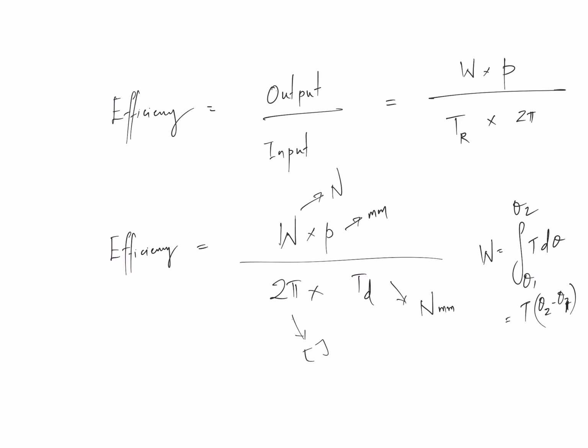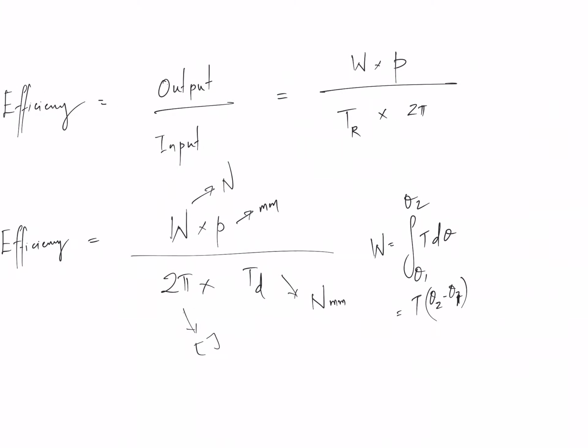Now let's look into the last portion of the question where they are asking us whether the screw is self-locking or not. Very important, whether it is self-locking or not. So for a screw to be self-locking, it means we need to apply a positive torque to lower it. On its own, it won't come down. It's good, right?